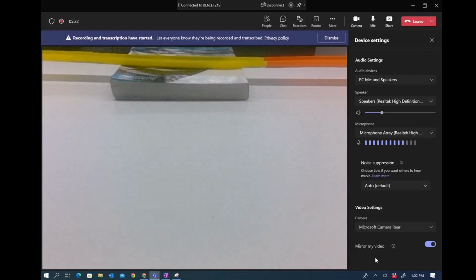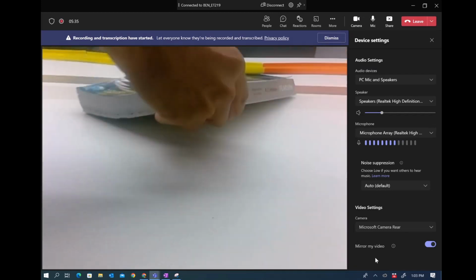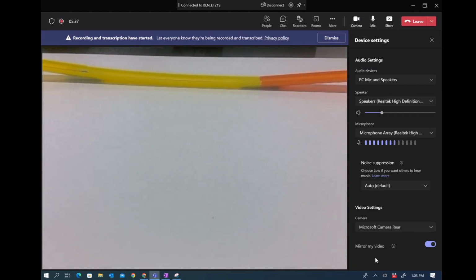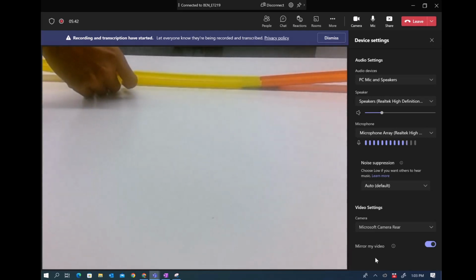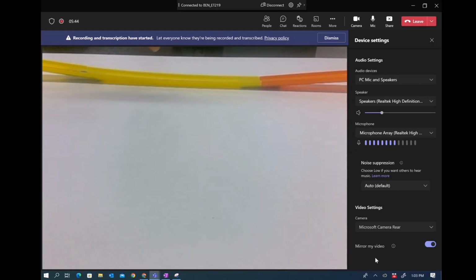For this beam, let's say you have a pin support at the left side, then roller supports, for example. OK, so that becomes indeterminate. Why do we make indeterminate structures? Because if I remove this book, look at that, how much deflection you will get. To reduce that deflection, you either increase the material strength or increase the cross section of the beam. You make 2, 3, 5 layers of that beam, and the deflection might go away. But that is expensive also, right? Adding material on top of steel is expensive.